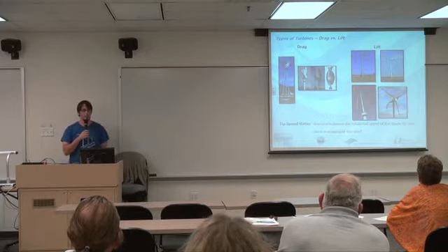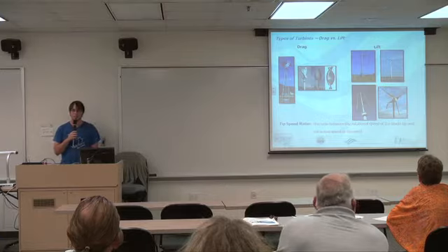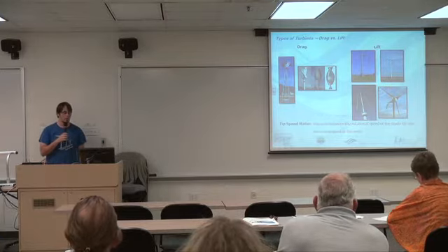But as far as electricity generation, it is not as beneficial, and that mainly translates to what's called the tip speed ratio, which is the ratio of the speed the tip of the blade is moving in comparison to the actual wind speed. The higher the tip speed ratio, the better you're going to do in electricity generation. For drag turbines, that's typically around a ratio of 1, because the blades can only move as fast as the wind is moving, since they are just working off the drag of the wind itself.